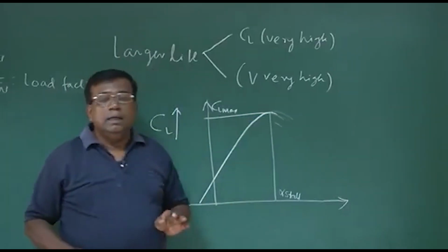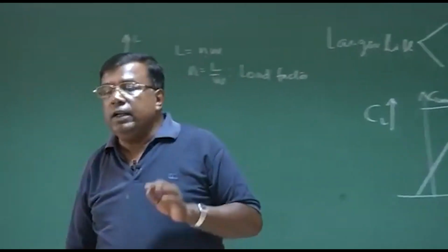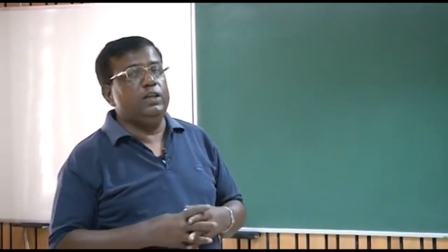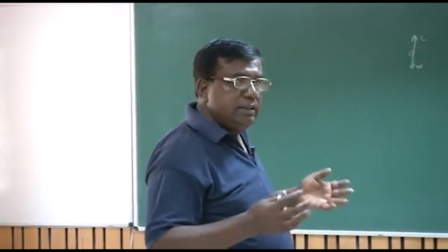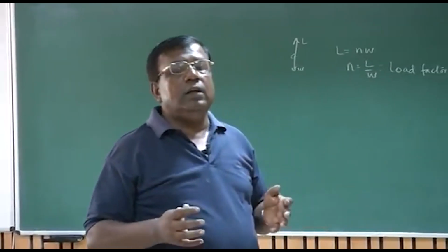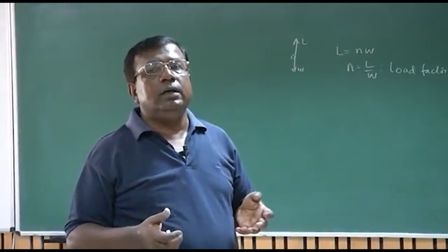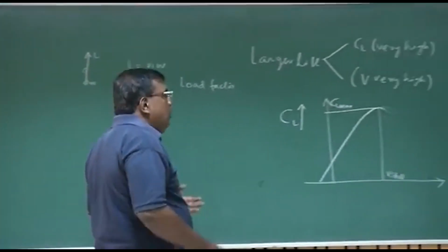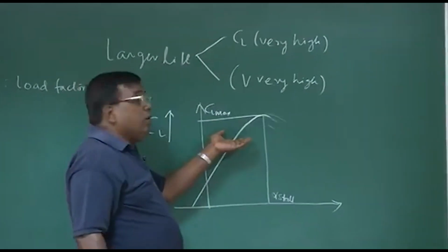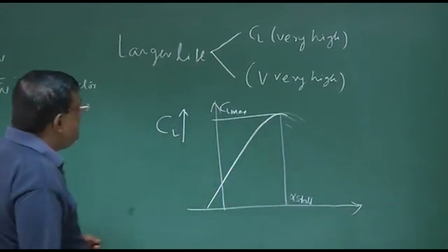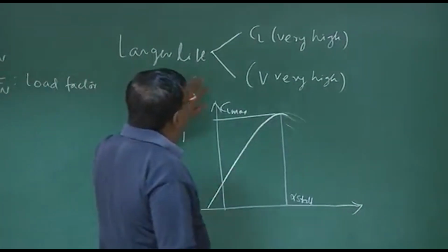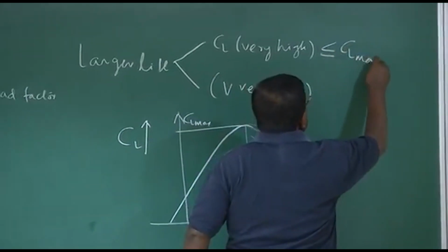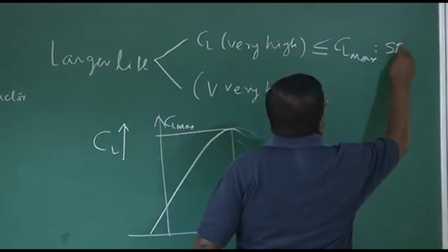But remember one thing, when I say that, it doesn't mean that if an aircraft has gone into a stall, I won't be able to recover it. A good designer ensures that, to a larger extent, if the airplane goes into a stall, the pilot should be able to recover it back to a stable or normal, non-separated, non-stall region, right? So I know that CL being very high is restricted by CL max, or by the need to avoid stall, right?